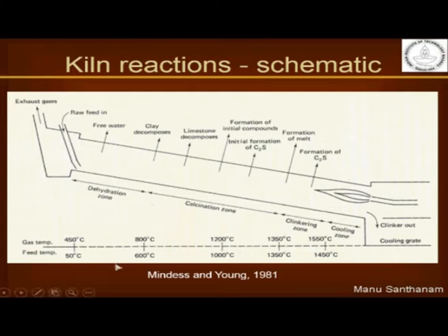Okay. So, this last stage of cement manufacture, or the kiln reactions, is very important. Here is when the C2S with additional lime, that is calcium oxide, gets transformed into C3S, and the reason that this reaction is promoted is because of the formation of this molten phase that has appeared at around 1350 degrees Celsius.